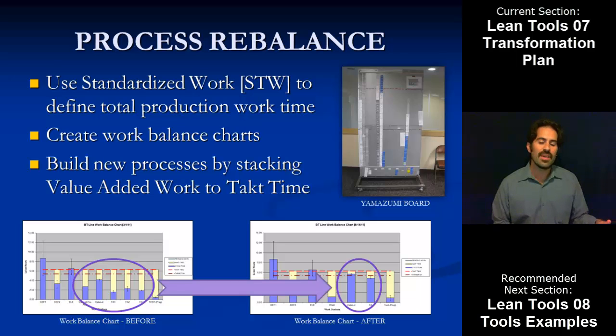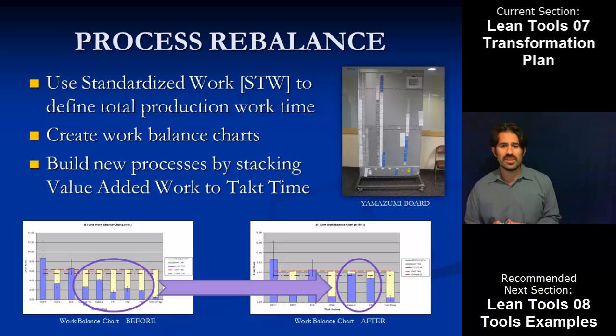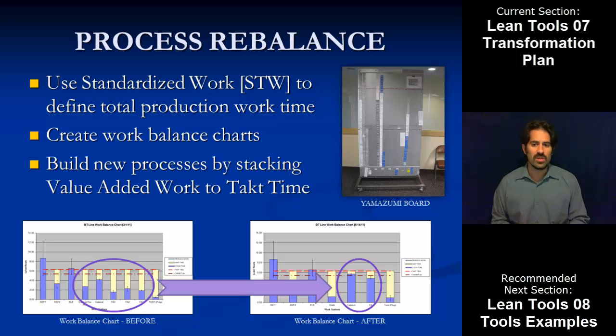So instead of 5 half people waiting, people in and out, now you have 2 full-time people just doing the same amount of work. And one of the tools that we use to do this is a Yamazumi board, which this is an example shown there. And all the Yamazumi board is, it's a way to physically represent standardized work that can be moved around easily